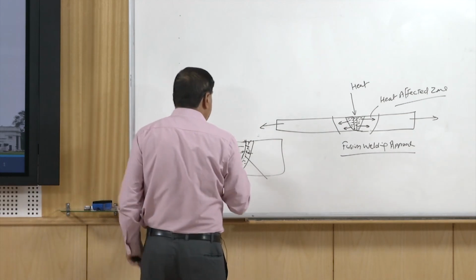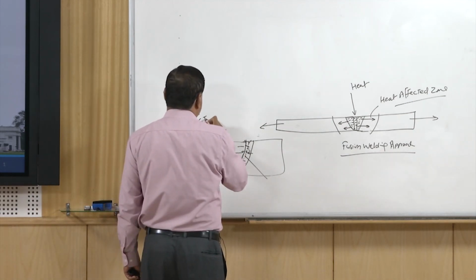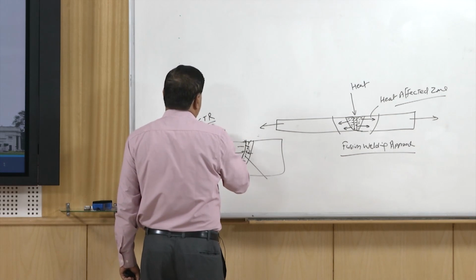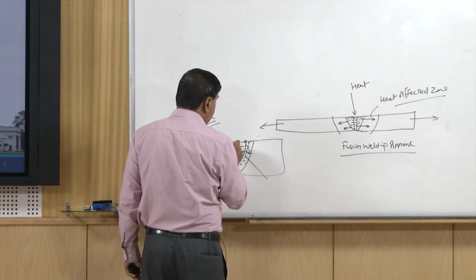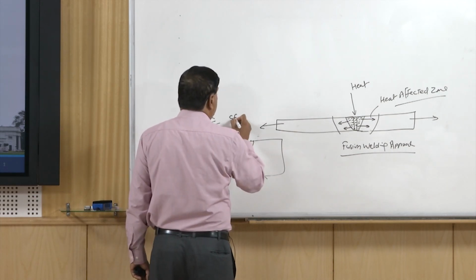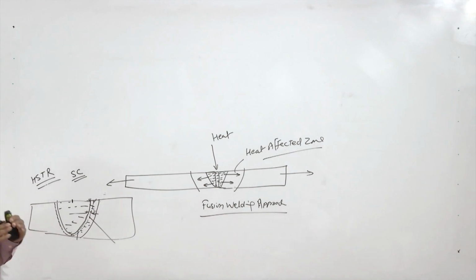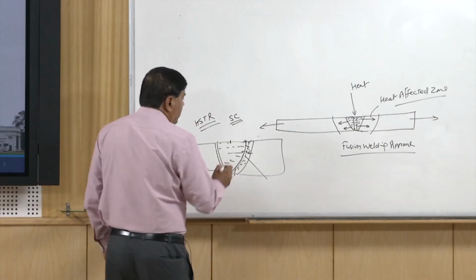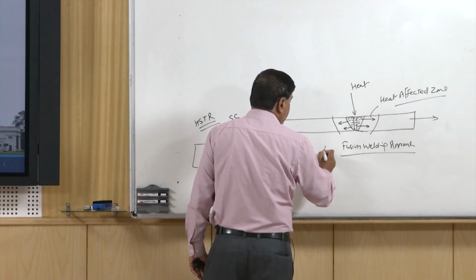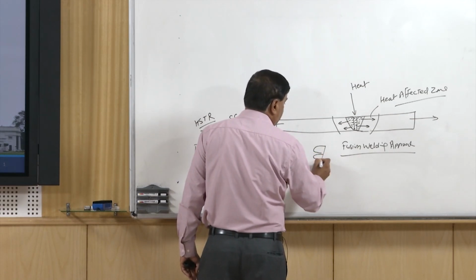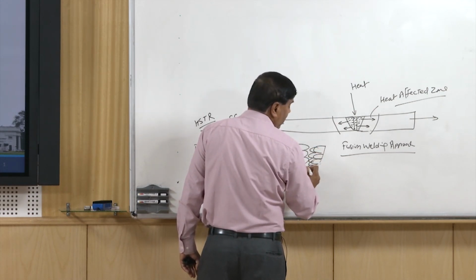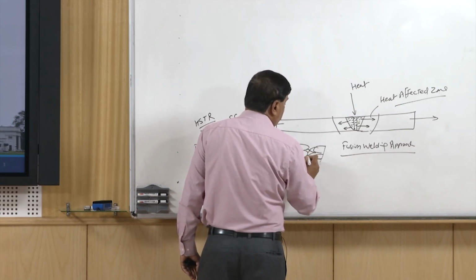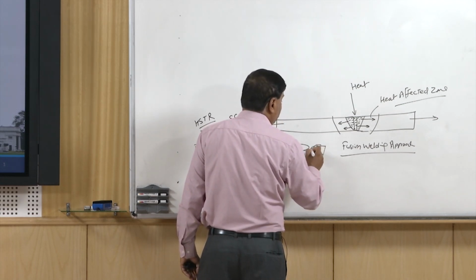High solidification temperature range metals also show the tendency for cracking at the center, which is called solidification cracking. Solidification cracking occurs when the weld metal starts solidification at the fusion boundary and ends at the center. So, in this case whatever liquid metal is left at the end to solidify accumulates at the center.